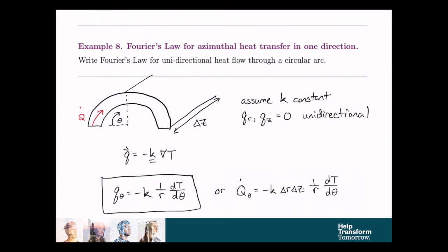That might not be intuitively apparent because it is a slightly strange way of viewing the problem, but you know that coordinate axes are always orthogonal. So if you want the direction orthogonal to theta, it's going to be r and z in that plane. And the shell I've depicted here has a delta r, which is sort of like the width of that rainbow, and a length, delta z. So think about it. You just plug that area into the expression for area in Fourier's law.